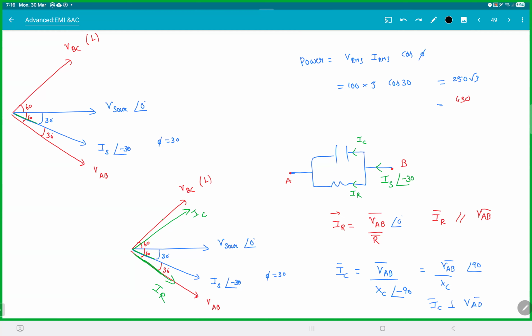So you do everything same, the junction law is same. I is equal to I1 plus I2, but make sure I1, I2 are vectors. Voltages will be same. In series, voltage is V1 plus V2, but V1 and V2 are vectors. So that is the main thing you have to get into the head. You have converted all these into vectors and you're just playing with vectors, right?